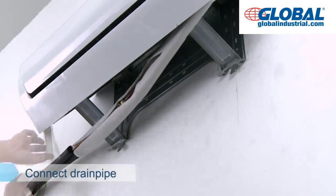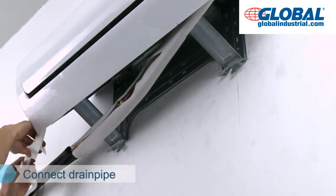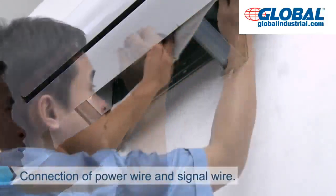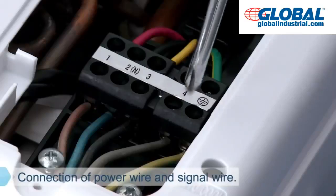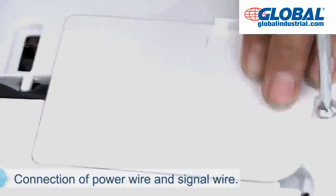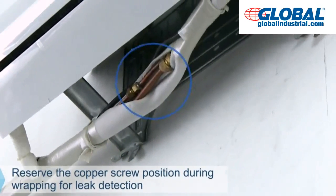Adjust drain pipe of indoor unit according to the reserved length of drain pipe. Note that the interface should be sealed with adhesive tape. Connection of power wire and signal wire. Wrapping is conducted in order where power wire and signal wire are at upper side. Connecting pipe is in the middle and water pipe is at lower side. Reserve the copper screw position during wrapping for leak detection.